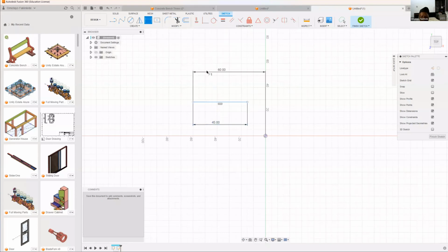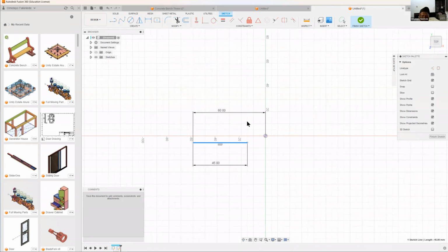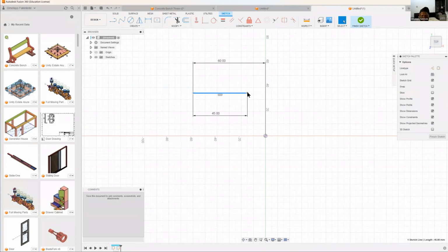Why is it still blue? Because I've already told it where it starts from, and I've already told it the length. It's still blue because the line can still go up or down, so it's still not yet fixed. So what do I need to fix this line? Let me now set the vertical location of one of the points, any point on it. If I choose the vertical location of either the beginning or the end point, then I would have fixed this object completely. Let us say I create a dimension again.